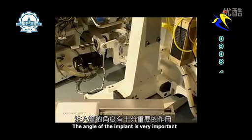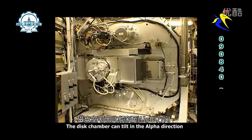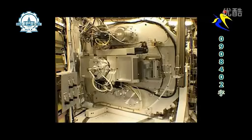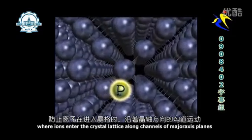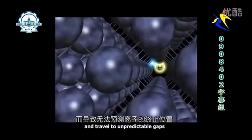The angle of the implant is very important. The disc chamber can tilt in the alpha direction or in the beta direction. This tilt of the wafer prevents channeling, where ions enter the crystal lattice along channels of major axes and planes and travel to unpredictable depths.